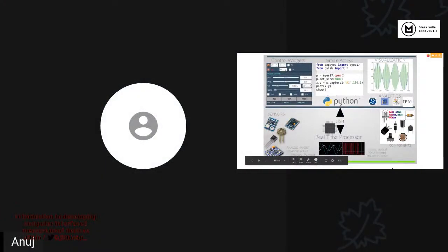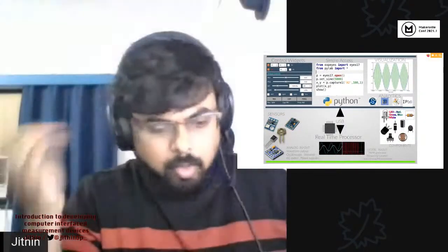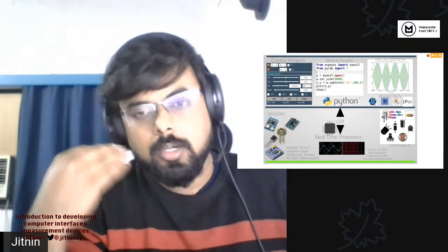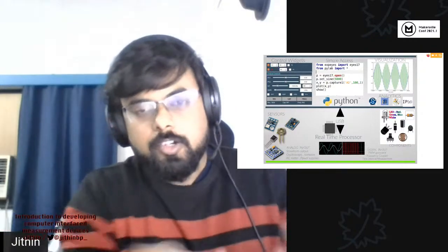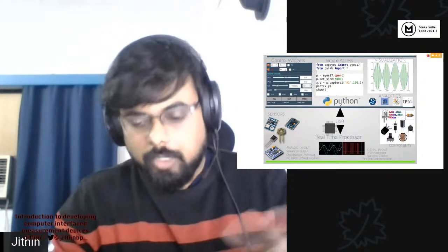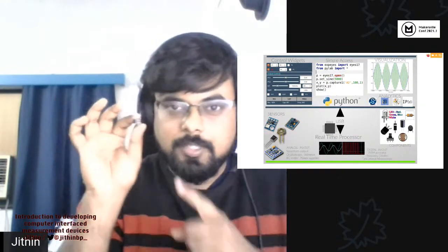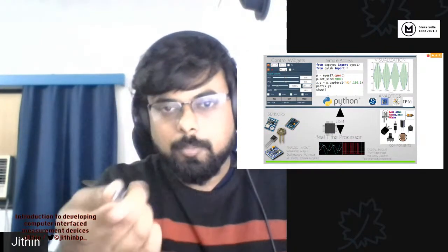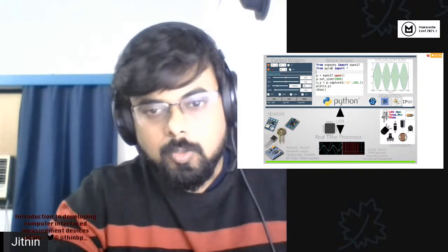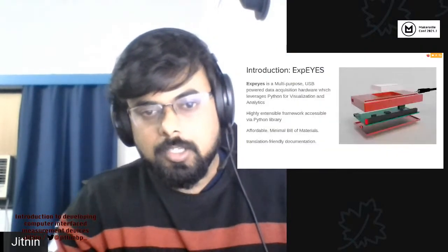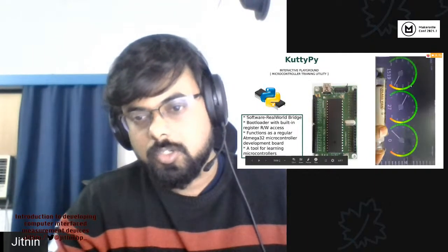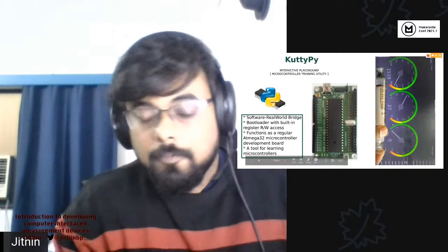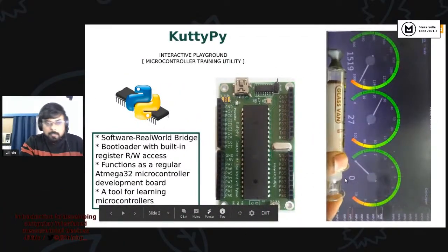And what it does is it has all the protocols for communicating with these sensors already written into it. So students can go on and use abstraction layers, like simple functions for, let's say, read humidity. And it'll return the value in RH units of whatever the humidity parameter is by getting data from the sensor through the instrument and to your laptop, where you can visualize it. So as shown in the previous slide, you could connect something here to this instrument and see gauges where this is pressure, this is temperature, and so on, for, let's say, physics experiments, electronics experiments, and so forth.